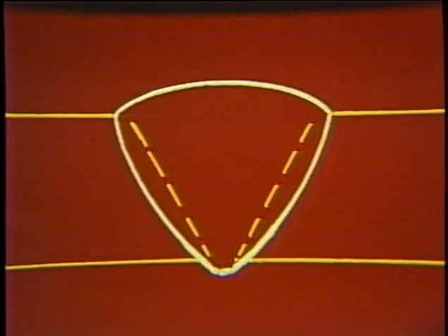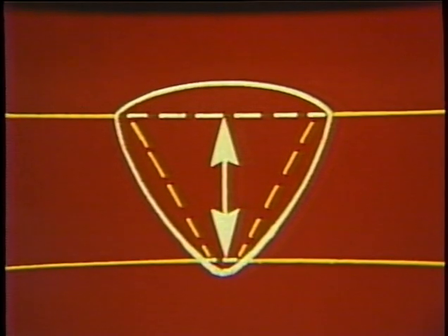Excessive root reinforcement is extra weld metal deposited in the root of the weld. This is generally more common with joint designs which have root openings. In addition to excessive reinforcement, welds may be unacceptable if they are incorrect in size. The size of a groove weld is measured by the depth of the effective throat, the shortest distance from the root of a weld to its face, minus any reinforcement. Generally, it is equal to the base metal thickness on full penetration welds.